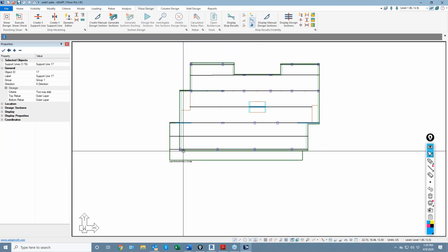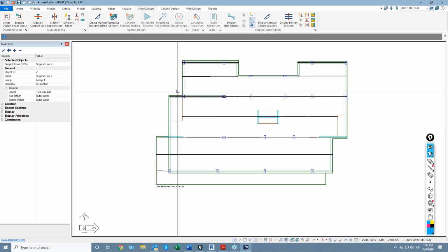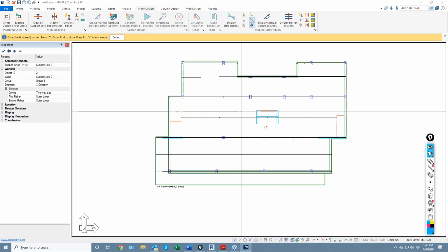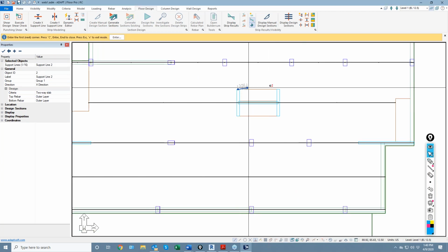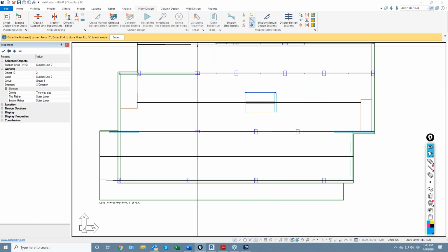Okay. And if we wanted to make sure that the strips don't encroach into openings, then I'll use a splitter. So I want to use an X direction splitter. I don't want the program to extend the design cut, for example, here down into this opening. Technically, there's nothing wrong about that in terms of just the result, the pure result. The program doesn't see any elements in this zone anyway, so it can't integrate over an element where there are no nodes. But again, from just a kind of a cleanliness of modeling standpoint, you may not want to see those section cuts passing through.